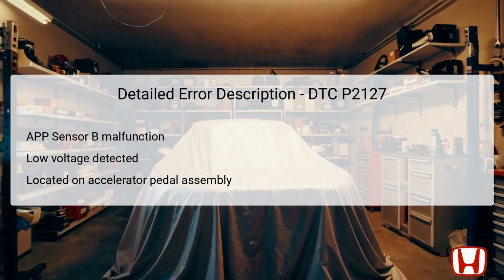When the value detected by this sensor falls below approximately 0.2 volts, it indicates a potential malfunction in the sensor or its connections. As this system directly influences how the engine responds to driver input, any issues can lead to reduced performance, increased emissions, and may trigger various warning lights on the dashboard. Understanding the context and implications of this DTC is vital for a comprehensive troubleshooting approach.